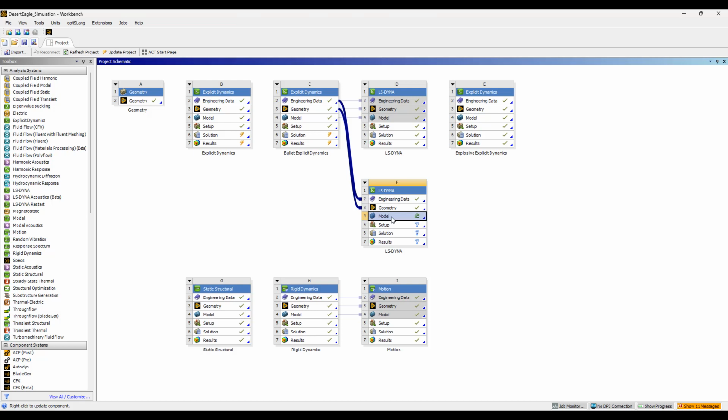So I'll be going into Ansys LS-DYNA as an example of using an explicit dynamics simulation tool to model the motion of different components. The big benefit of using explicit dynamics is its ability to capture arbitrary contacts. You don't have to predefine any contacts or connections.